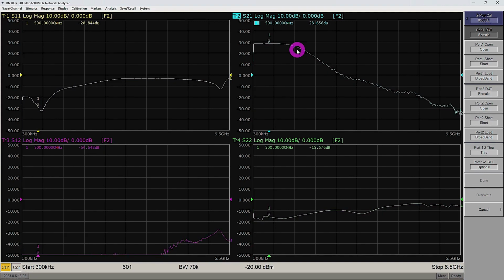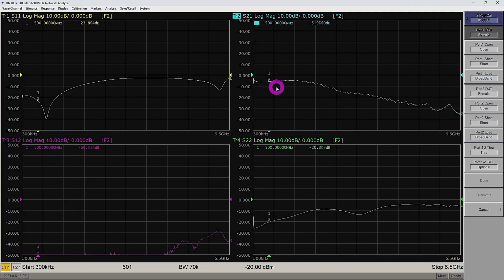Now what I can do is change the way that gain control is done. I can apply a square wave to it. And if I apply a square wave, I would expect this to jump up and down depending on whether on the high side or the low side of the square waveform. Let's just go ahead and apply that. So here's our square waveform. And we can indeed see that this is a 1 Hertz square wave, and the gain jumps from about -5 to +28. So there's a 33, 34 dB of gain control, which is great.